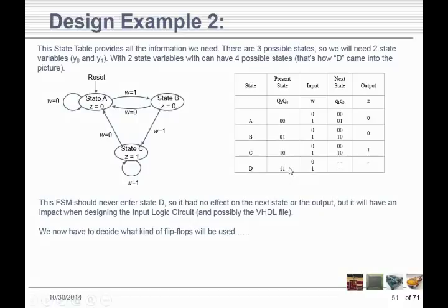So there's nothing wrong with choosing different state variables, and then I've only got the possibility of one bit changing. When I go back to A, I've got one of those situations where 2 of them are getting reset and I might get a glitch. But again, our output is associated with our present state, and you can see that they match up with what we had before.